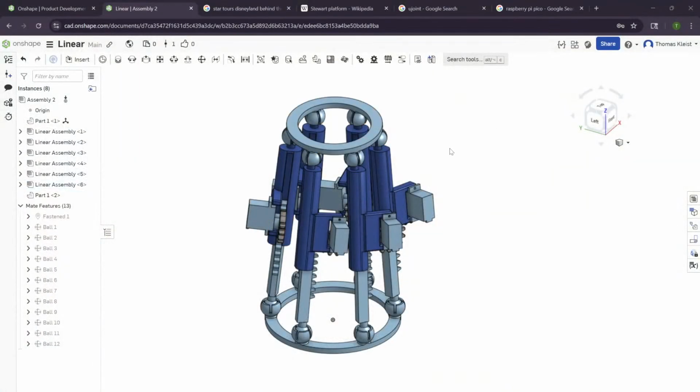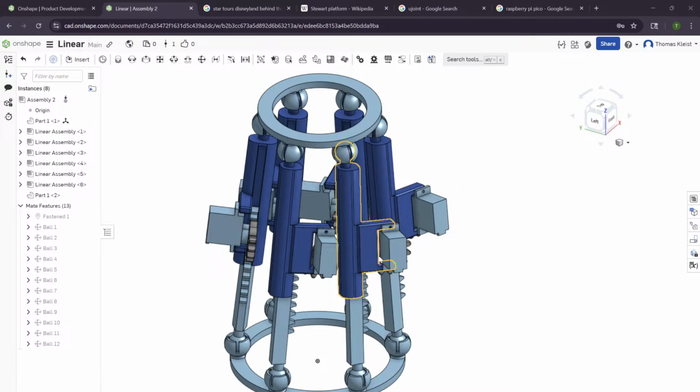So just like this, I'll replace these ball sockets with U-joints. Hopefully it doesn't require too much rework of the design. Honestly, it might actually only need one side to be U-joints. Because if only the bottom is a U-joint, it's still constrained axially then. So there won't be that rotational motion, and the top side can still be the simpler to construct ball joints.